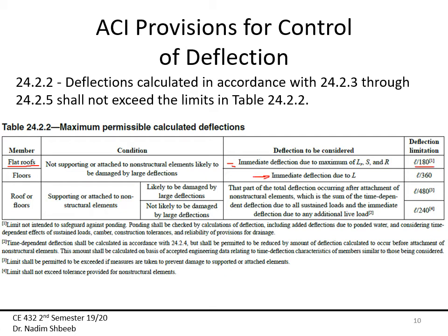If I'm only concerned about immediate deflection due to live load only for floors, then that limitation is L over 360.